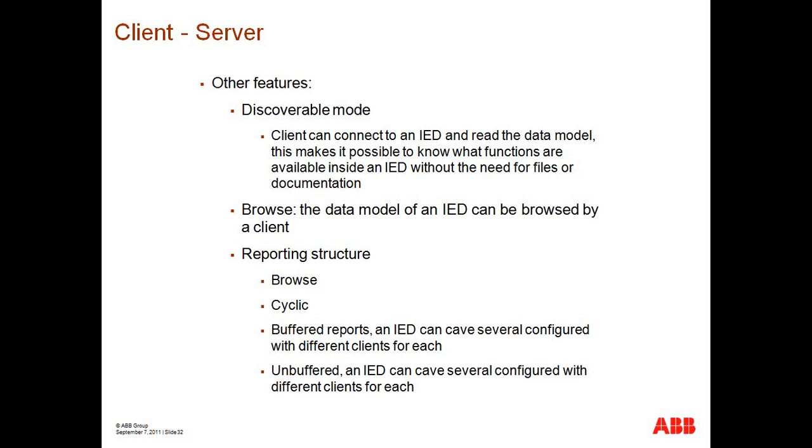So again, without needing a protocol implementation manual, I can download the data model from this IED, browse through it, and see the status of each of the points that's part of that data model. Or, in 61850 terms, look at the status of the different data objects within a particular logical node.